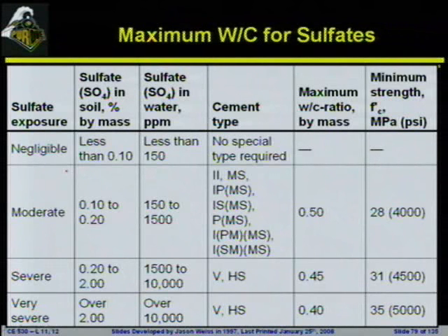When we start to look at our maximum water to cement ratio, we've talked a little bit about how it's related to strength, but there are a couple other durability factors that we need to start to consider. And these will be mainly related to freezing and thawing, corrosion, and sulfate attack. And what you will see here is the water to cement ratio is going to be incredibly important depending upon the level of exposure, because water to cement ratio is going to determine how things move through the system. It's going to dictate the transport properties of our concrete.